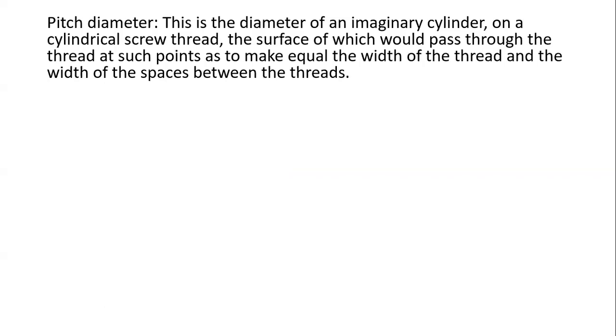Pitch. The pitch diameter, of course, is the diameter of an imaginary cylinder on a cylindrical screw thread, the surface of which would pass through the thread at such points as to make equal the width of the thread and the width of the spaces between the threads.